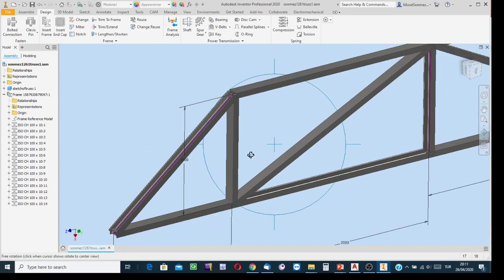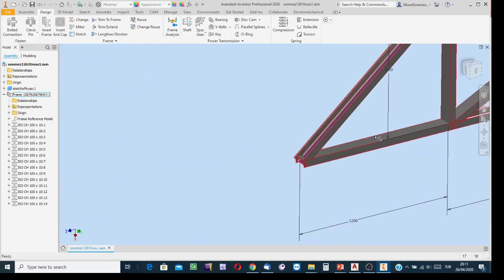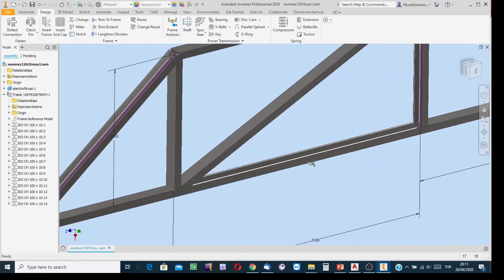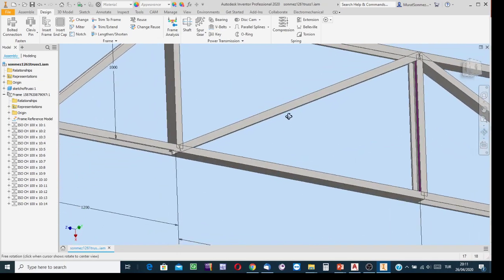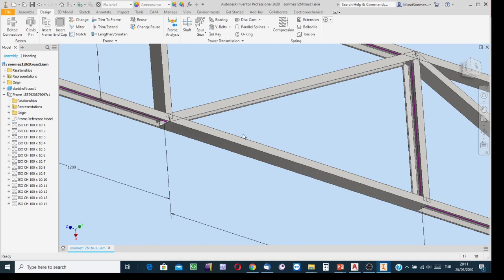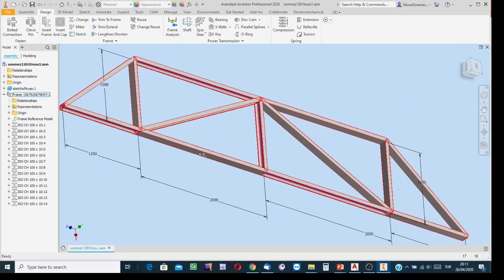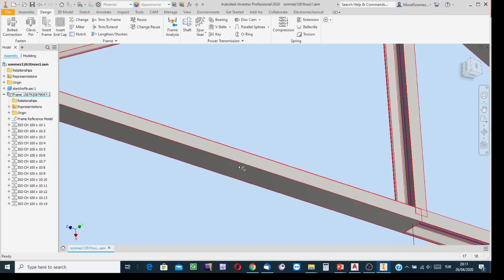Creating the truss, my purpose is to orient the member like this. No, not like that. Like this one. The flat surface of the member is to be positioned horizontal and toward the surface of the earth. You see the cross section is U shape, C shape. But here my purpose is to have the member oriented like this. The positioning of this member is correct. Its flat surface is toward the surface of the earth.